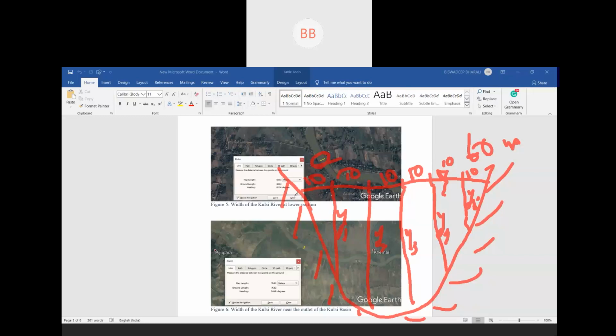So we are going to find out the area. This will be the area. How are we going to consider this? This is a triangular section. As this is an irregular shape, we don't have any defined calculation to find out the area of an irregular shape. So what we do, we divide it into a number of sections, and the first and last one we consider to be triangular sections, and all the others we consider as trapezoidal sections. And we find out the area.